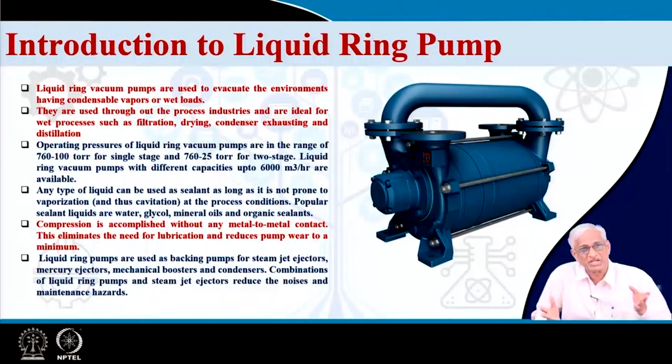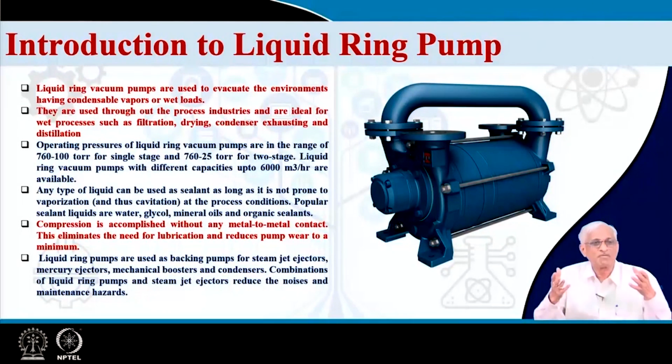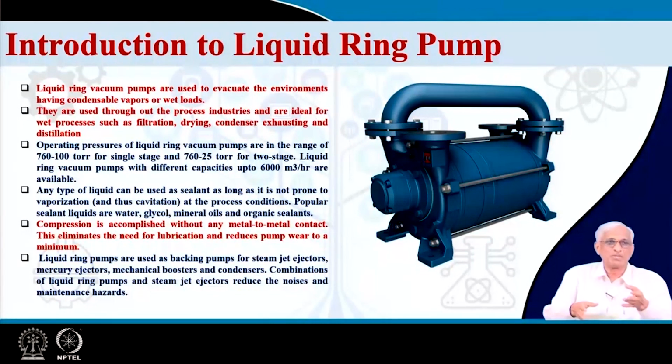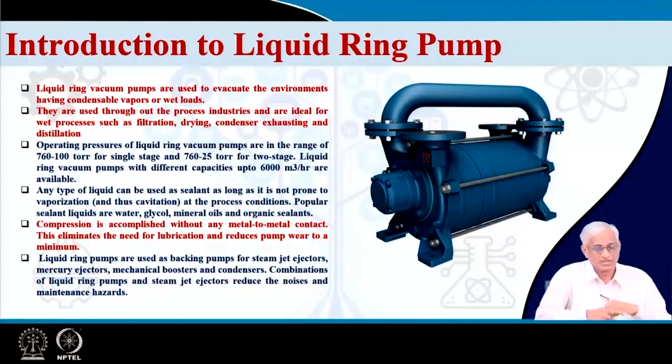The vapor pressure of the liquid will finally settle the issue, because you cannot get better vacuum than the vapor pressure of the liquid, which is going to do the role of an expanding chamber, compressing chamber or sweeping chamber, etc. That is the reason you can use different oils if you want to get different levels of vacuum.